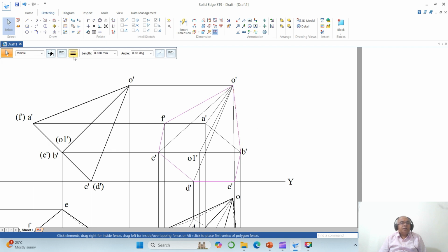Okay. Then you mark this as 0.5. The surface near to the observer is visible. This edge becomes visible. So make it 0.5. From a point, if only one of the edges is visible, automatically the other edge also becomes visible. Okay. And two visible edges can never cross each other. That is, this point and this can never become visible, so it will be hidden only.